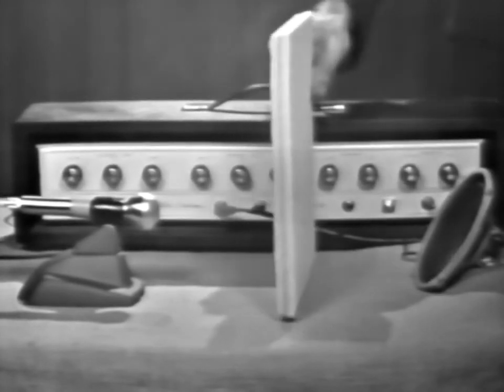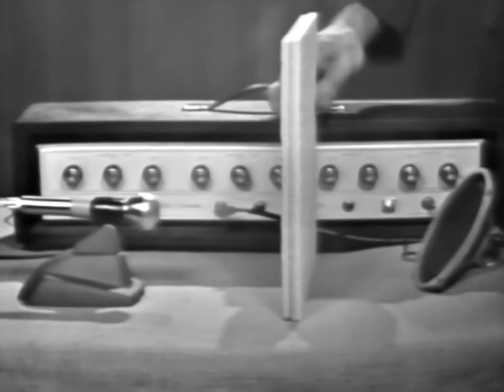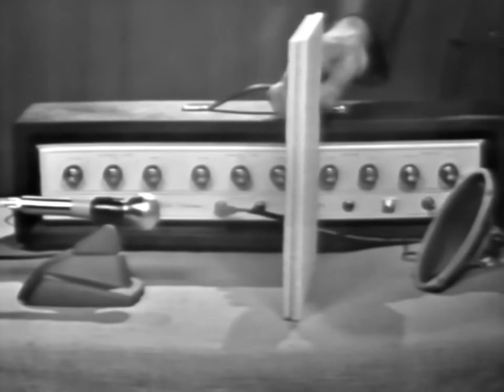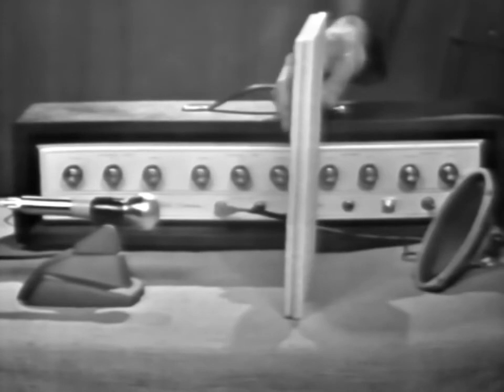The squeal builds from a relatively low level to a very high level. And if allowed to continue, very high oscillating currents are built up that may damage circuit components. For this reason, the amount of feedback must be controlled in an oscillator. The correct amount is just enough to overcome the losses in the circuit.